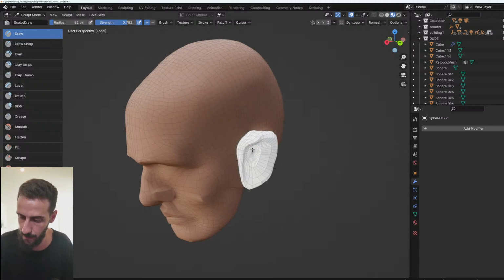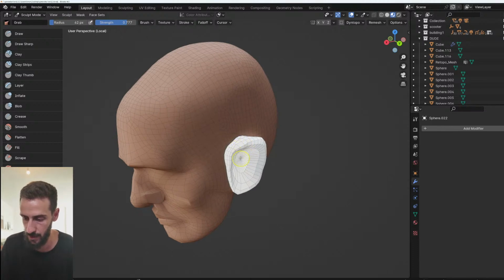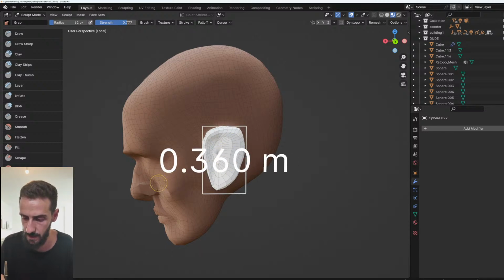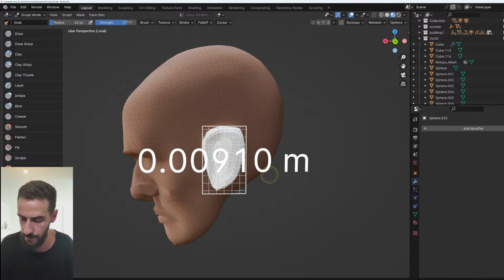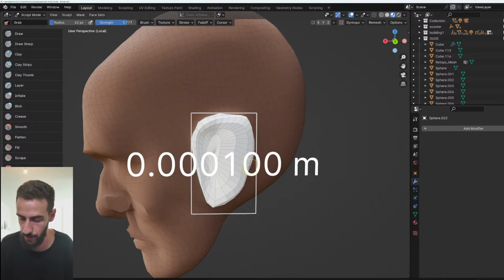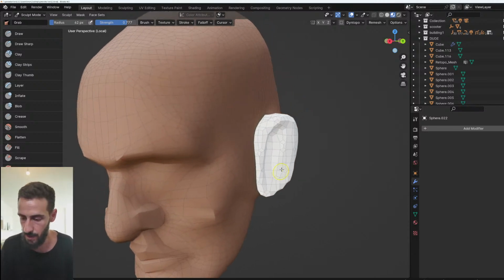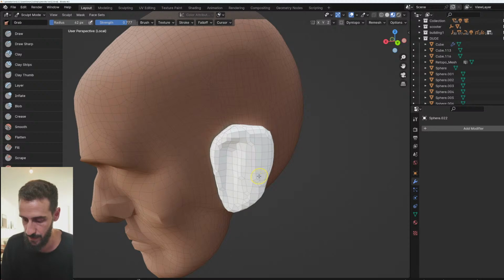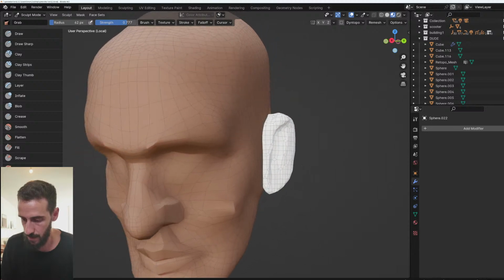Anyways, all right, so here we have a weird geometry topology, which is not gonna work however we push it. You just have one point and everything is concentrated around it. What I'm gonna do is press R for resolution, and we're gonna make it smaller. And this is technically the size of the faces that we'll end up with after automatic remeshing. So this is R, and then if you press Ctrl R, you remesh it. It's big, let's go for something smaller. It's still big. R, Ctrl R, it's fine for now.